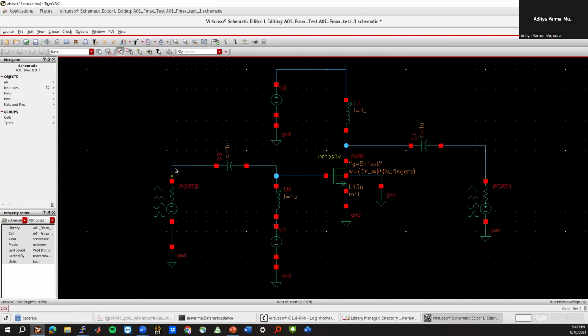When I have RF coming in here, it's an open here, so it doesn't go there, it goes in here, and then generates a current in this circuit, and the RF current flows through this because this is short and this is open, right? And then the DC path sees an open on this side. DC just goes through this transistor. And the same way here, this DC goes and directly biases this, right? It doesn't see this output. So that's the idea. This is like a bias T. Essentially just 2 bias Ts.